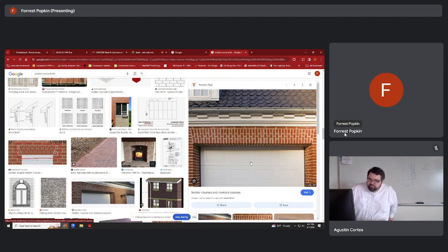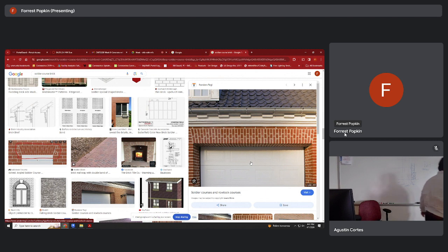So here's my criticism as an architect, is that now everything's done with smoke and mirrors. The brick isn't actually holding up my building. Okay? This is face brick, and it's all being held by structure. There's probably a glulam beam here doing a lot of the heavy load lifting because it's such a wide opening, and there's just normal standard lumber on the edges. But visually speaking, if I took the same horizontal brick and went this way, my eye would look at that and go, it's just floating. Because there's nothing that's supporting that.